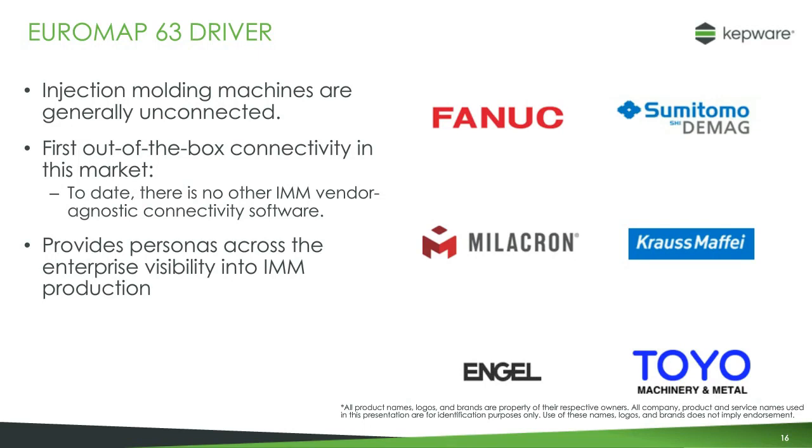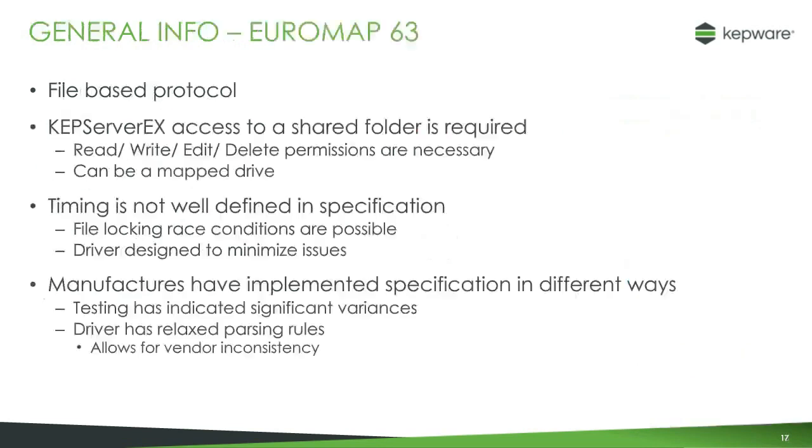Information about the protocol itself, it is file-based. This means that KEPServerEX needs to have access to a shared folder where both the machine or the machine's software will be able to pass files between KEPServer as well as itself. It's important that permissions are set up appropriately for this driver so that KEPServer has the capabilities to read, write, edit, or delete those files that are placed.